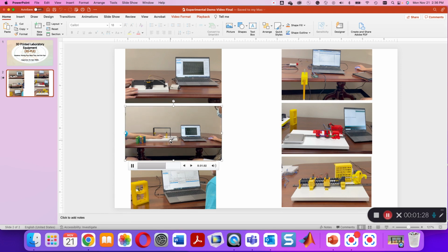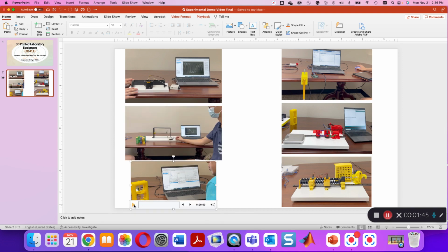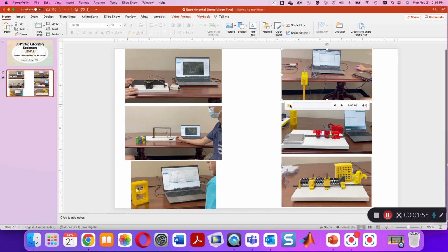Again, free vibration means that from the moment you start the motion by displacing, even by applying a force at the tip for a cantilever beam, or for a slider displacing it to the right or to the left, and then releasing. For a rotational disc, you just rotate the disc, because this is also a single degree of freedom system, and once you release, you are not applying a force anymore. Here is another one. We have a pendulum. This is also an example of a 1 degree of freedom system. You can just rotate it to an angle and release from that position, and collect data